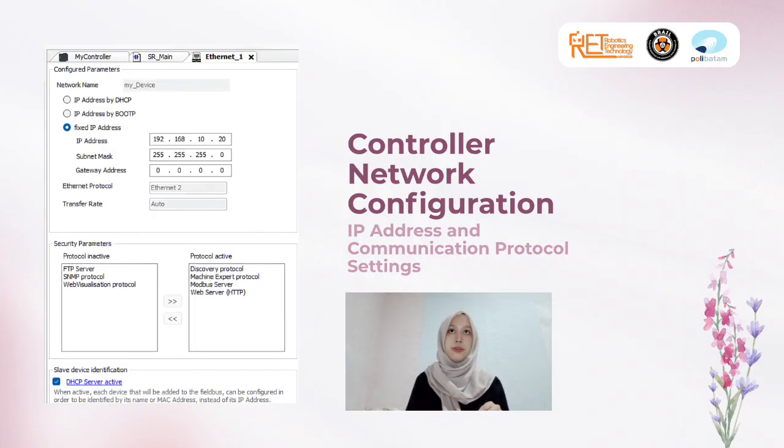This has also been done before in our practice module. If I am not wrong, it's in our 8th practicum. And just like when I set up the IP address on my PC earlier on, I also made sure the Windows firewall on my computer wasn't blocking the connection to the PLC. This matters because if the firewall blocks the traffic, the PC and the Factory I/O won't be able to reach the controller at all, even if the IP addresses are configured correctly.